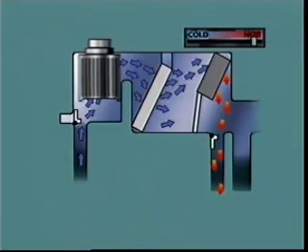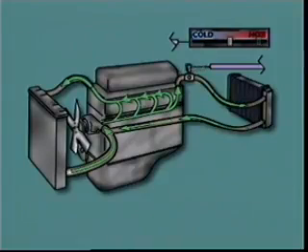When the engine is at normal operating temperature, some of the heat in the heater fins is transferred to the air passing over them. The heated air can then be directed to raise the temperature in the passenger compartment. Moving the lever to obtain a cooler temperature setting reduces the valve opening. This restricts the amount of coolant flowing through the heater core. Less heat is then transferred to the air passing over the heater core fins.